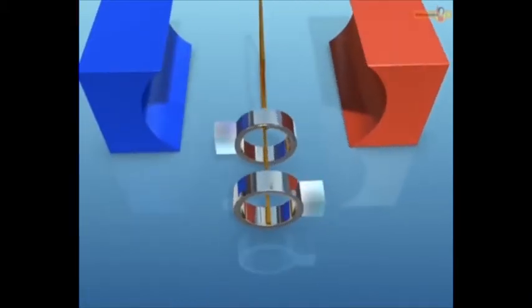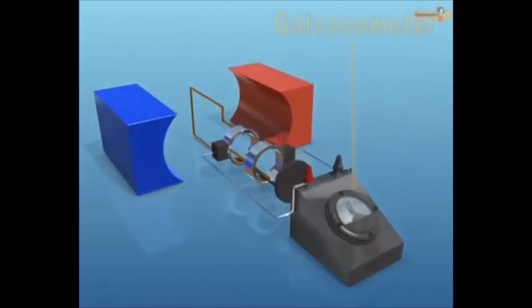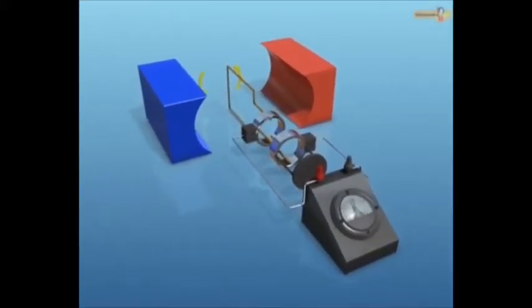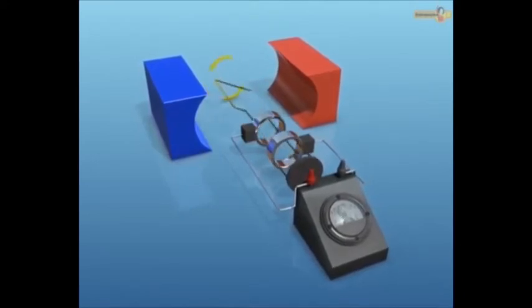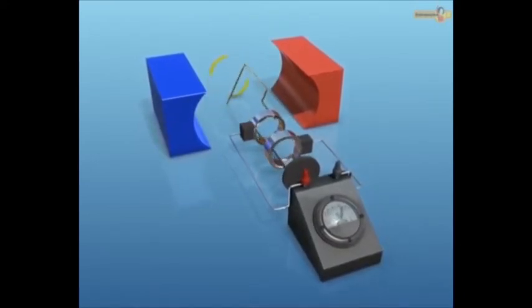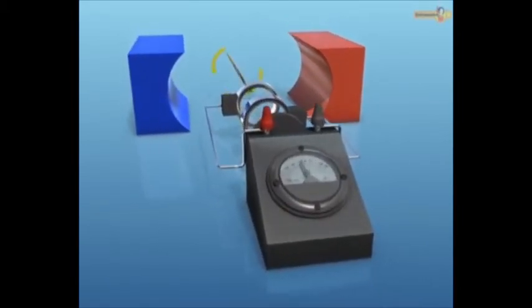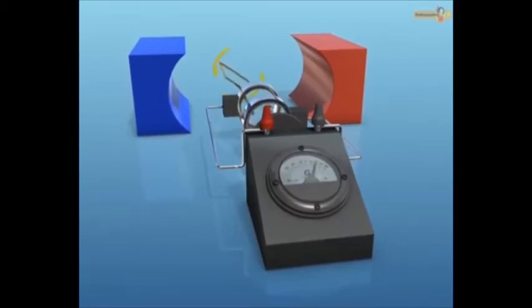Two brushes are made of carbon. One end of each brush is in contact with the rotating slip rings, and the other end is connected to an outer circuit. A galvanometer is connected in the outer circuit to show the deflection due to the current induced in the armature. When the coil is rotated between the pole pieces, a current is induced in the coil. The induced current is shown by the deflection in the galvanometer. The two-way deflection in the galvanometer shows that the induced current is alternating.